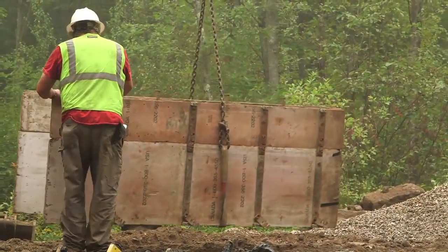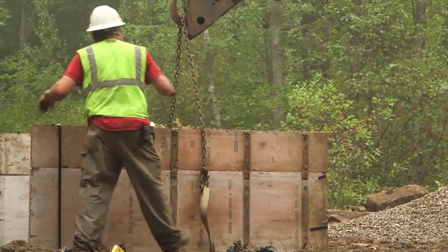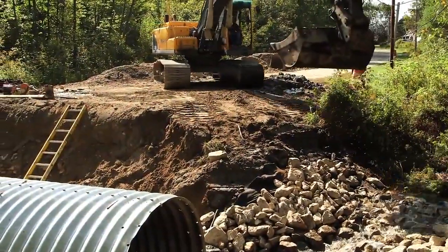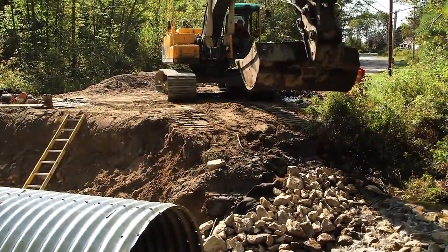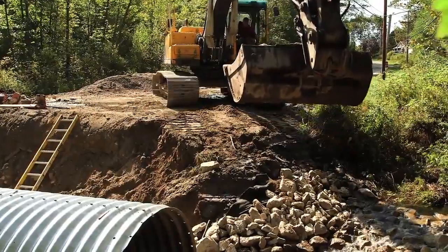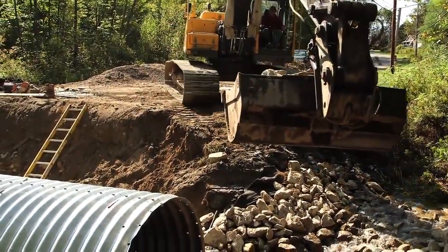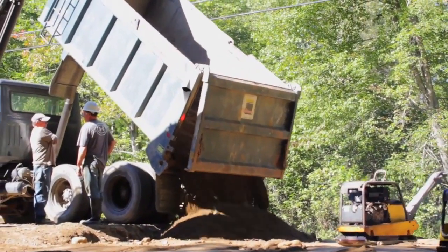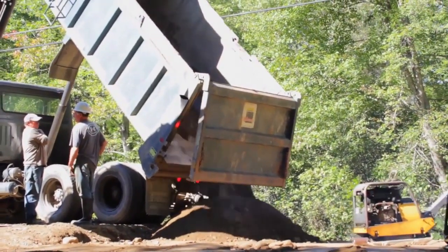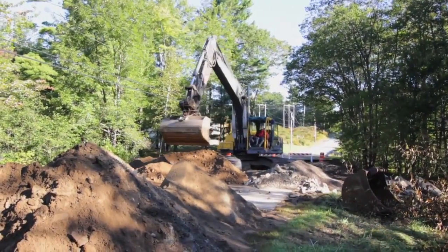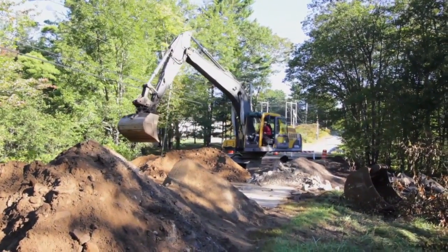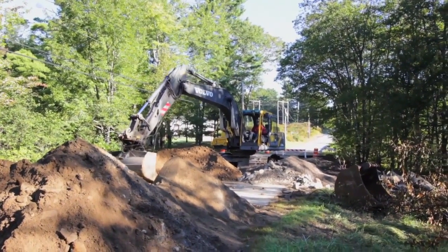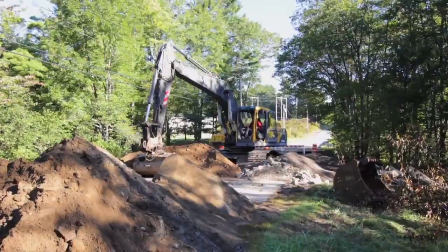Materials needed to construct the concrete footings and place the culvert should already be on site when they are needed. Required earth and gravel fill needed for the backfill of the culvert and road construction associated with the culvert should be stockpiled on site as much as possible. There are typically on-site storage limitations for the entire earth and gravel fill needed for the construction site. However, stockpiling at least some of the earth and gravel fill can save time during the installation, especially if the earth and gravel source is a long distance from the site.